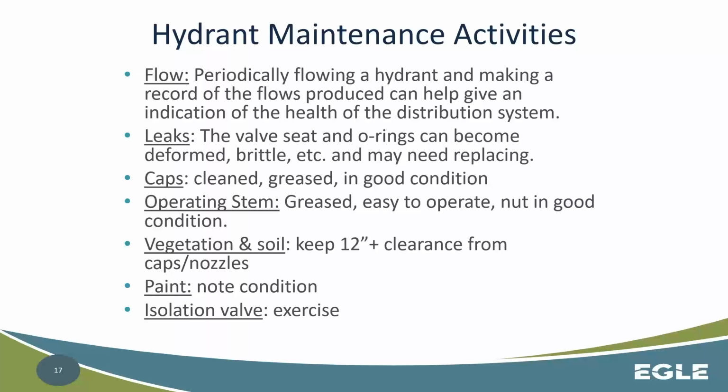our climate, where we have winter operations, if you have plugged weep holes on those hydrants and your barrels fill over the winter, you can get them froze up solid and cause all kinds of problems. So we want to know when there's leaks. The only way to know when there's leaks is to get out there and open and close a hydrant and make sure you can see that the flowing conditions have stopped.